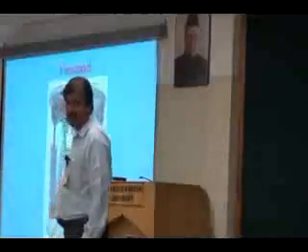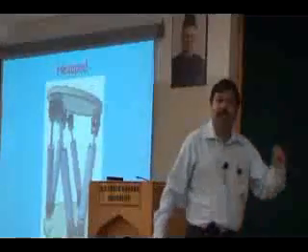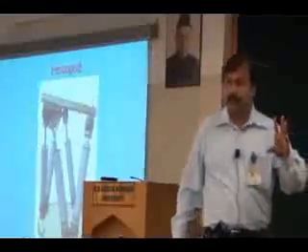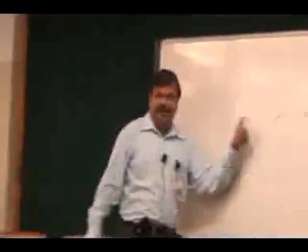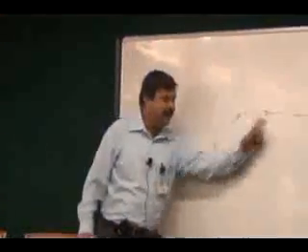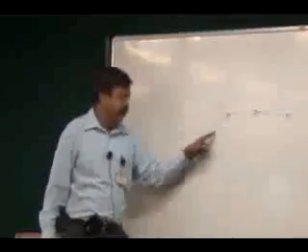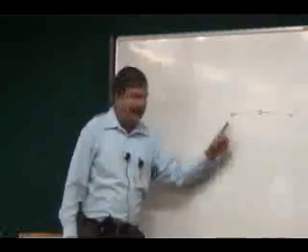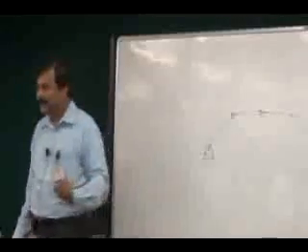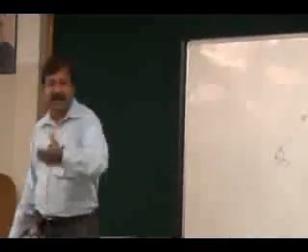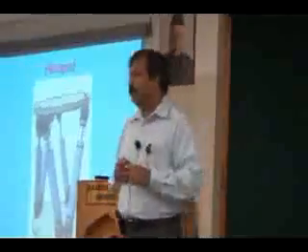All motions will be carried out, when we go back to the previous slide, all the motions will be carried out by the hexapods. Because the hexapods are more accurate. Because if we make a small change in the error, please remember that the error is going to be magnified subsequently. If we make a small error in the angular position at the base link, that will get magnified when we have a serial arrangement.